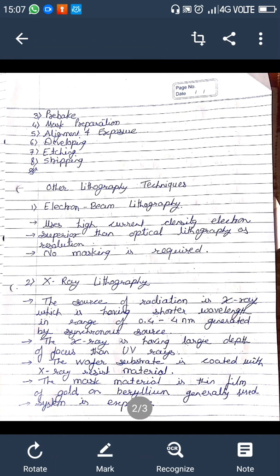There are two types of photoresist. One is called positive working photoresist and the other is negative working photoresist material. In the case of positive working photoresist, the dark region on the photo tool specifies the area that needs to be etched. And in negative working photoresist, the photo tool specifies the areas that need to be protected from the etchant. Generally, negative working photoresist is mostly used.